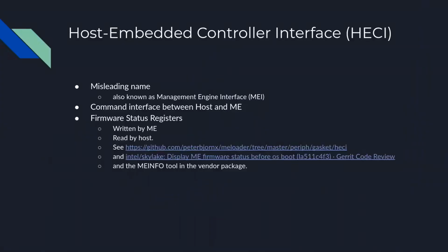And there's the host embedded controller interface, which is how the ME talks to the rest of the computer when it wants the computer to know that it's talking. So it can directly access a lot of stuff, but when it wants to send a message to the EFI or to Windows or Linux, it'll use this. And it also has status registers, which are really simple things where the ME writes in a value, and even if the ME crashes, the host can still read the value, which is actually how you can see whether the ME is running, whether it's disabled, whether it fully booted, or whether it crashed halfway through, but at a point where it could still get the rest of the computer running.